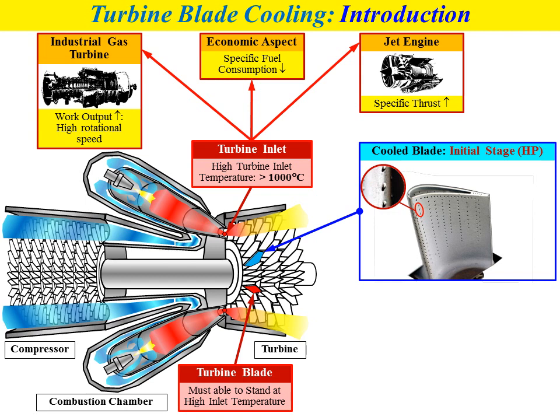We have examples of holes fabricated on the surface of the blade, holes at the leading edge of the blade, and holes at the trailing edge of the blade. These holes are used to supply cool air in order to form an air film surrounding the blade profile, so that the temperature of the blade can be reduced.